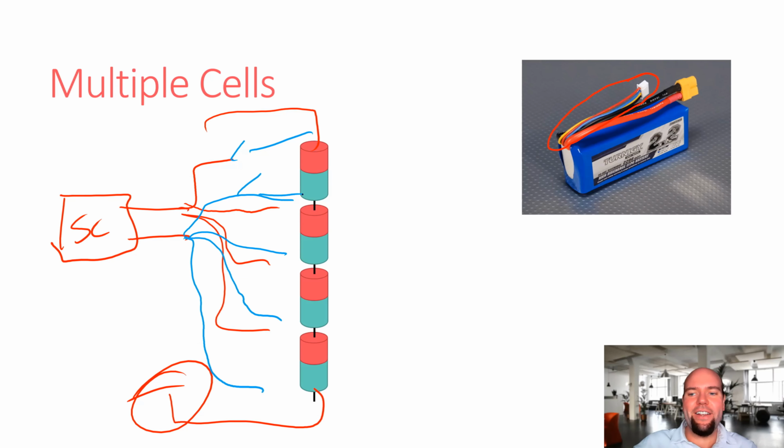You know, you get the idea, right? So basically you close the proper switches. So you charge one cell for a little bit, and then you jump over the next cell and charge it for a little bit and jump over the next cell. And so this means you only have to have one isolated charge circuit.